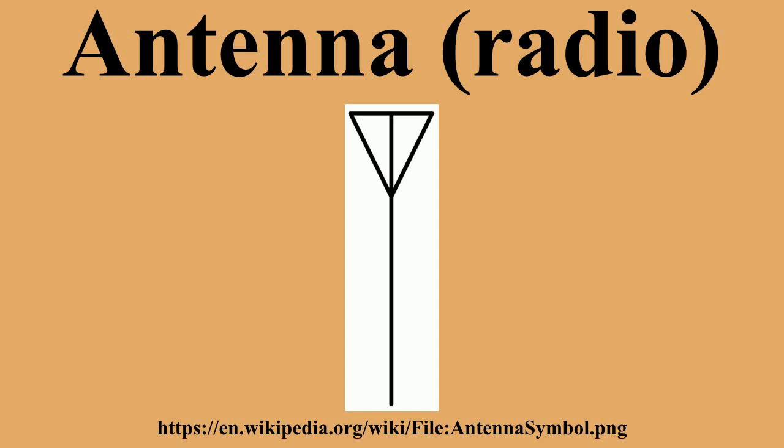One example of omnidirectional antennas is the very common vertical antenna, a whip antenna consisting of a metal rod. A dipole antenna is similar but consists of two such conductors extending in opposite directions, with a total length that is often, but not always, a half of a wavelength long. Dipoles are typically oriented horizontally, in which case they are weakly directional. Signals are reasonably well radiated toward or received from all directions with the exception of the direction along the conductor itself. This region is called the antenna blind cone or null.